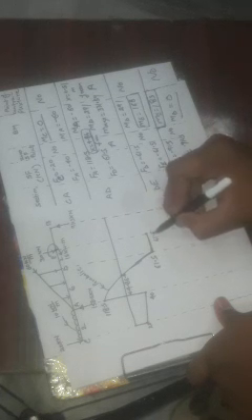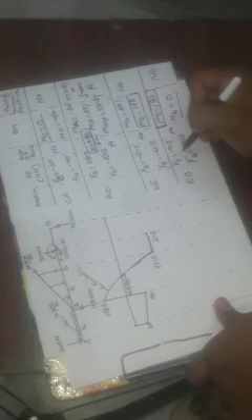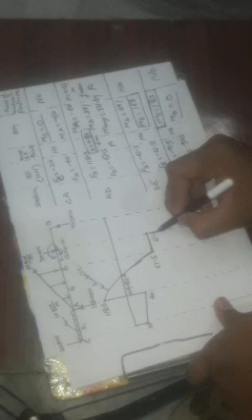Now at D, for portion D, the value is minus 61.5. Here for portion D there is a point load, so it is constant. At E the value is 61.5. Now at E it is 91.5. 30 is added here, so this will come this way, and here the value is 91.5, and at B it is 91.5.